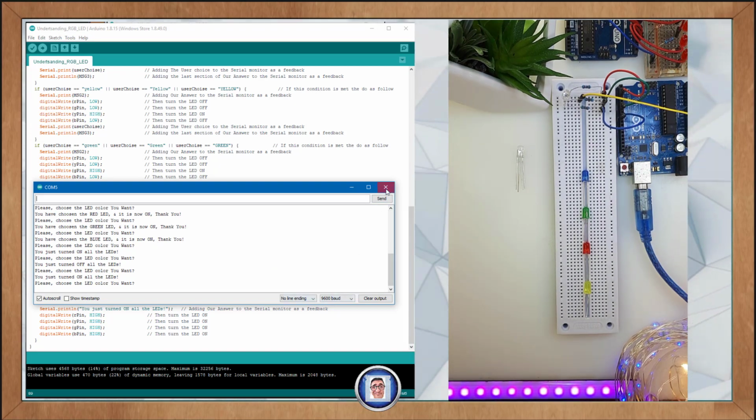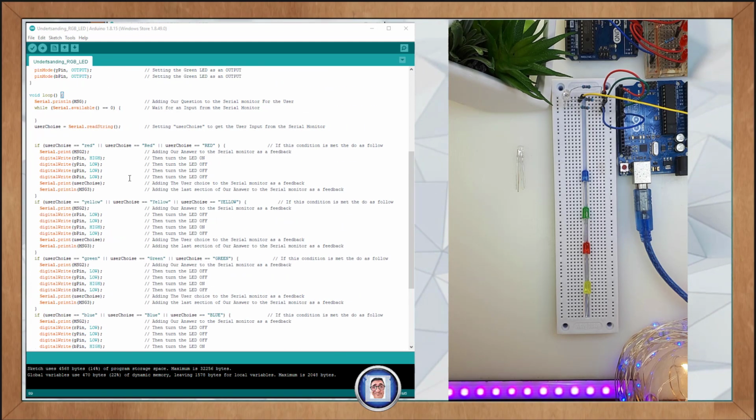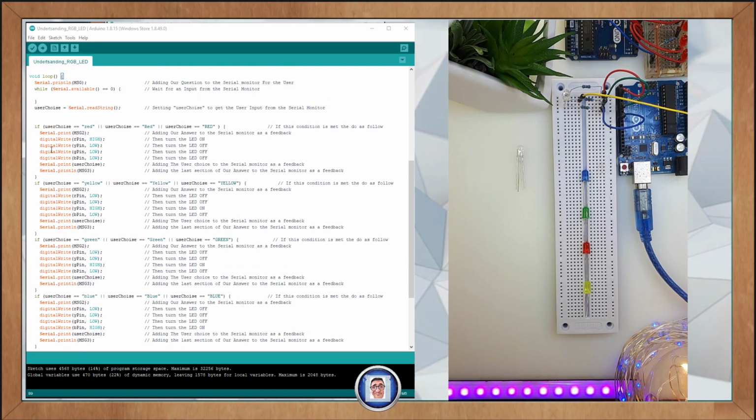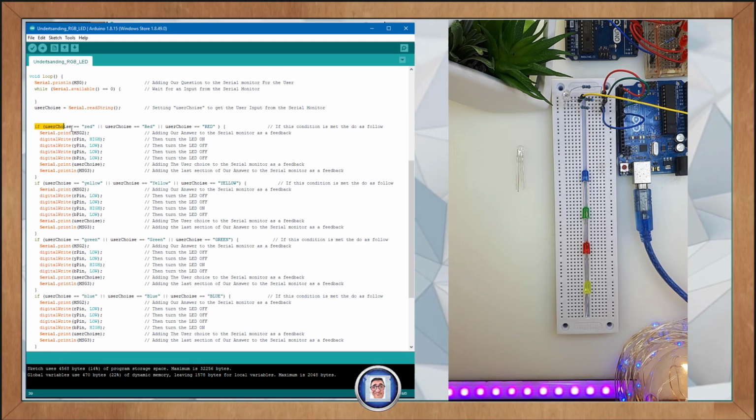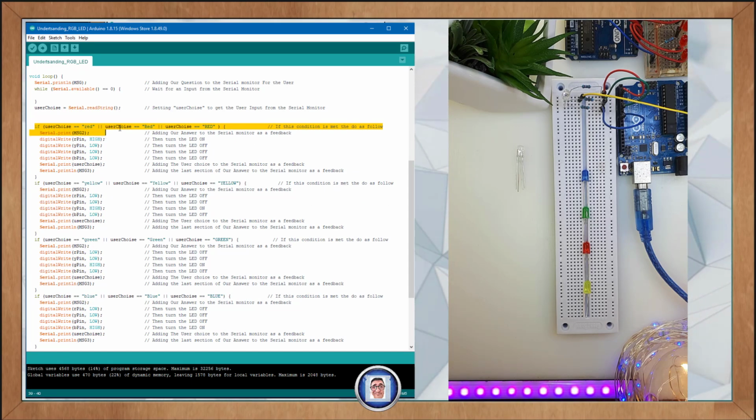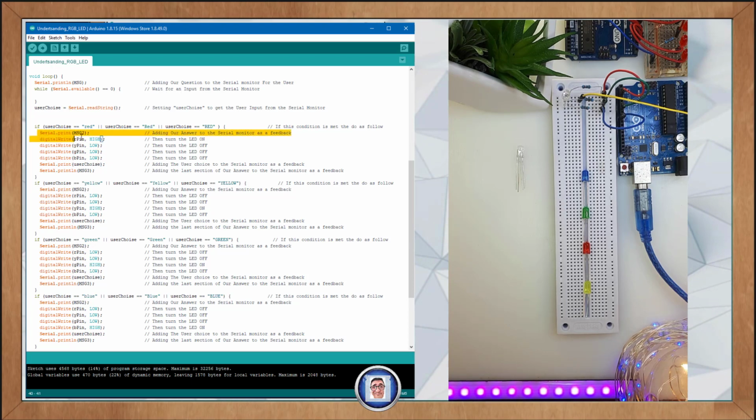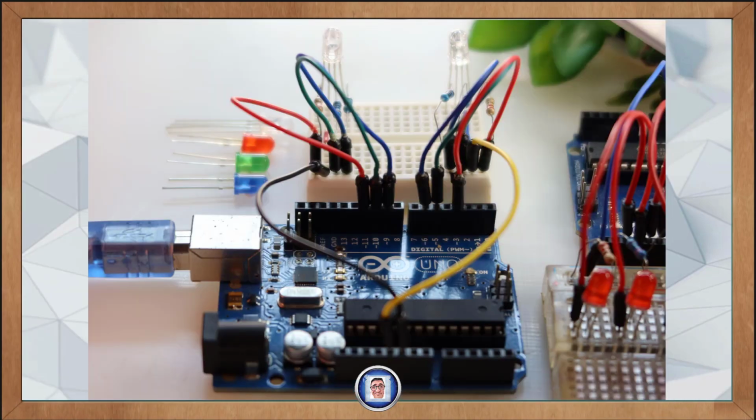Let's close all of this to understand what's happening in the code. And if we remember, when we turn it on, it turns off. Basically, if you are using an anode, you have to inverse everything in the sketch. So high would be off and low would be on. And of course, once we change this one, don't forget to copy it throughout the sketch.